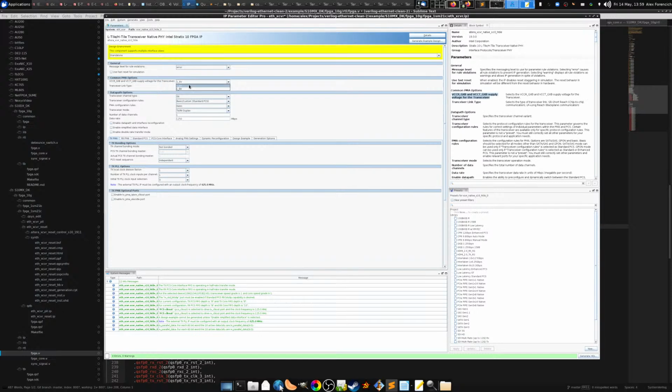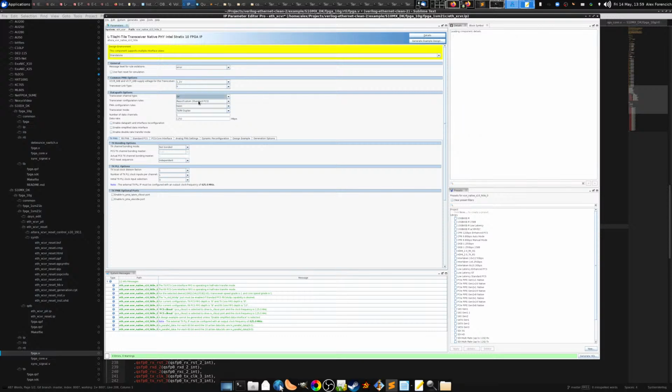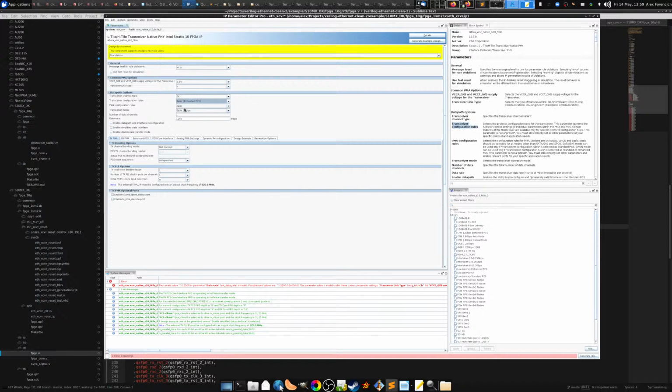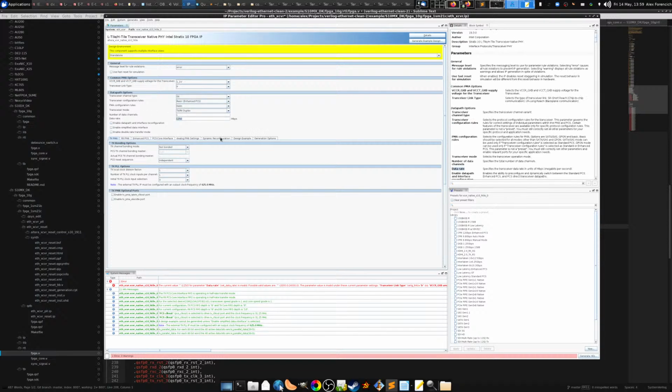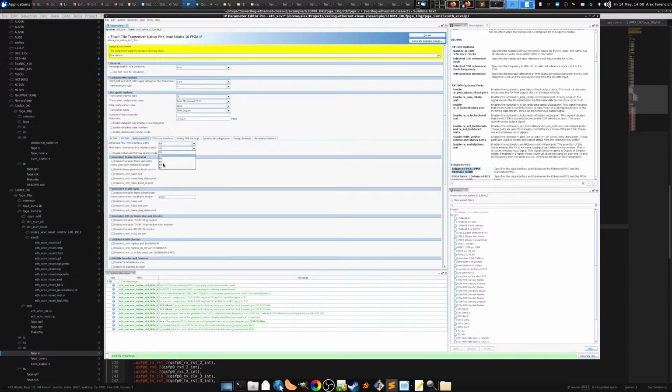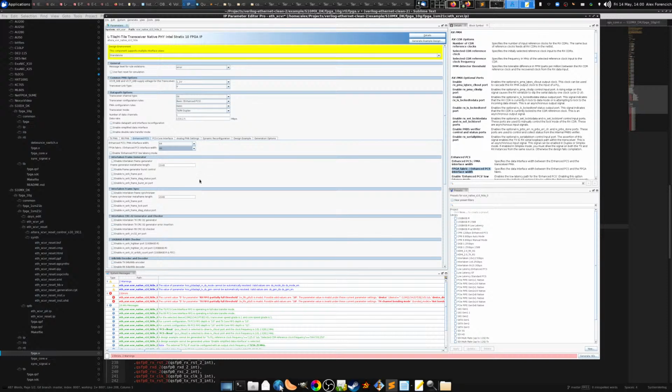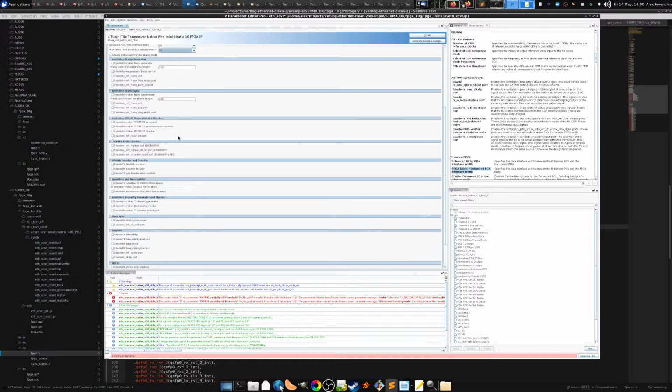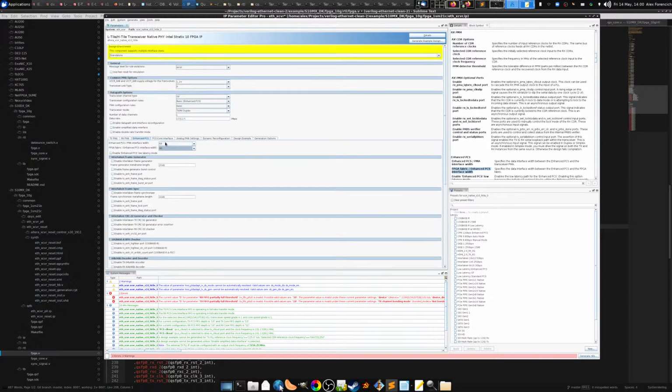This is done. All right, this is running again. Let me just go through from memory what all of the settings need to be for this to work. This GX, that's fine. Enhanced PCS. Okay, there we go. Basic TX/RX duplex, 1 channel. This is 10.3125. So this is going to be at 644, right? That looks good. This PCS sets it to 64 and this to 66. That will turn on, like I was talking about before, the gearbox so that we have a nice 66-bit output. What else do I need here? I don't think anything else.